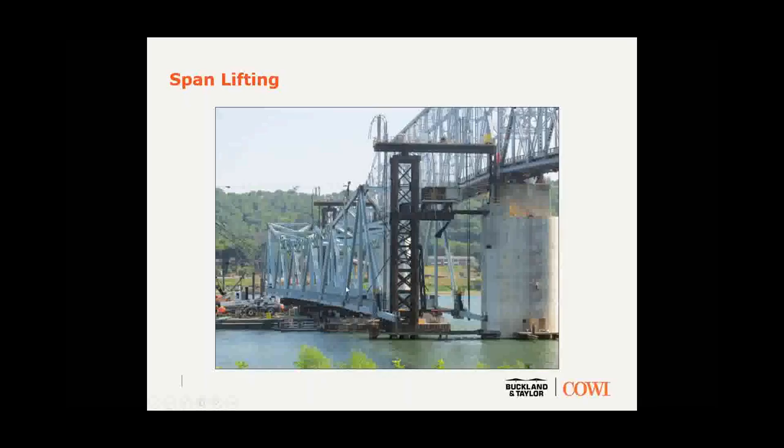The floating span had 2 bottom chord sections cantilevered out from it because they're, of course, part of that node assembly. And it had to be maneuvered around the temporary pier. Everything was carefully checked ahead of time to fit. And then the connections were made here and here to lift it, and then similar at the other end. So it kind of came in like this and then backed up again to the other end until everything was in line with panel points.